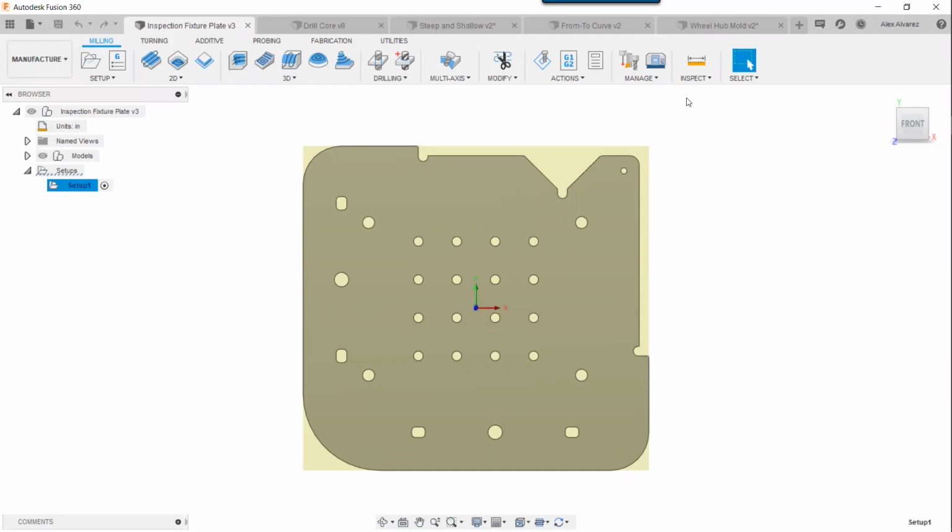So what a lot of companies do, or what a lot of machine shops do, is they'll actually create these huge fixture plates where they can essentially drill holes. They can either tap specific holes in specific configurations, and then they can start bolting down their parts, either for work holding, or maybe you want to do part verification with some of these fixture plates. But point being that these plates have just a lot of drilled holes and tapped holes.